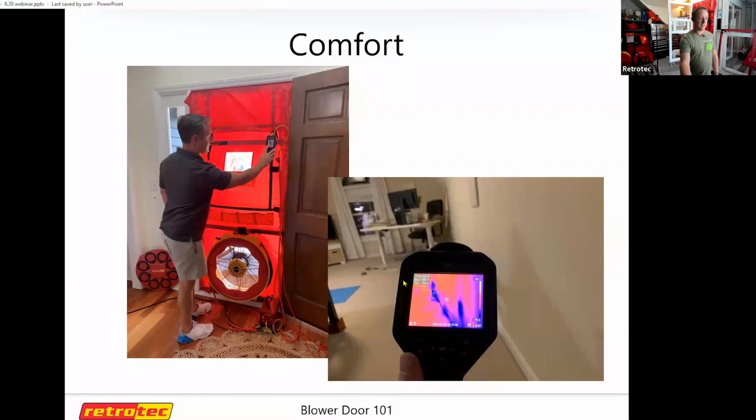So this is a bonus room, actually right up there. It's my wife's office. And what we're having to do is go in, this is a knee wall. On the other side of this wall is attic. And so there's just not really a good air barrier here at the bottom. So all kinds of outdoor air is able to make its way in. So having to build some scuttles here so we can get in that attic space and seal that up.